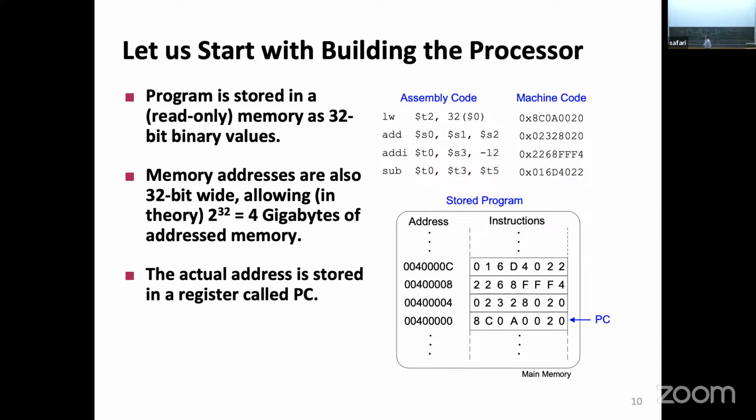You're back. After I've explained the exam questions, now let's continue. So, the program counter. What happens to the program counter? Well, the program counter normally will end up getting incremented every cycle by an adder. And it's actually very simple. It will get incremented by 4. Why? Because every element of this instruction memory is byte addressable again. So the next instruction will be an address 4 away from the previous one. So we just add to it, and there we have the next program counter, as simple as that.